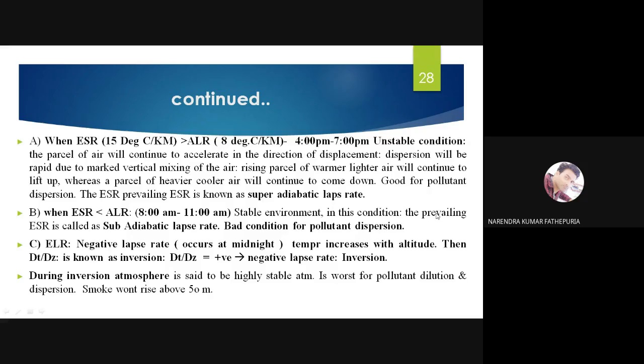In this condition, the prevailing ELR is called a subadiabatic lapse rate, a bad condition for pollutant dispersion in the morning. So generally in the winter season, we get fog and all that. I will talk later about the fog, how the inversion takes place and all that. So this is a bad condition for pollution dispersion.